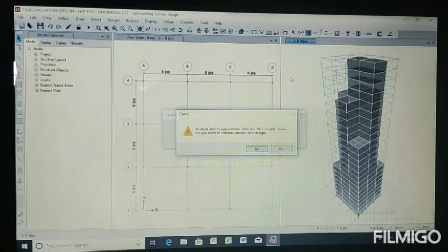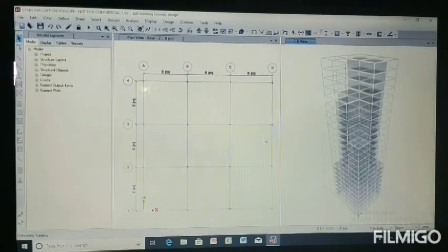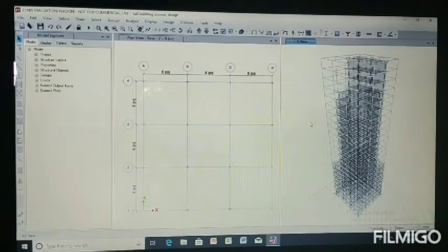Since there are about 703 concrete frames that differ, you can also reiterate it by clicking here, because we have the auto select for beams and columns of the other 2 dimensions. We can also reiterate it. The values are obtained after reiterating. We can click anywhere and we can see the reinforcement details also here.